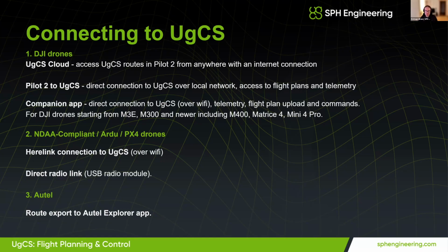Then the second is regarding NDAA compliant or ArduPilot PX4 drones. Here you typically have one of two options. Either you have some controller with an integrated screen. The most common one here is the HereLink controller. With this, you just connect the same way you connect DJI drones. You put it on the same Wi-Fi as the computer, and the drone will connect.